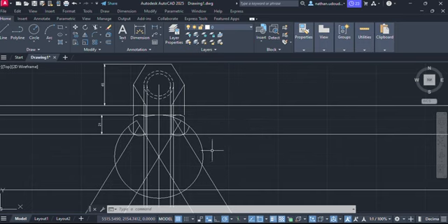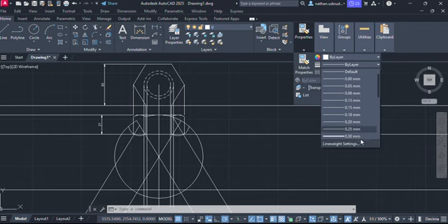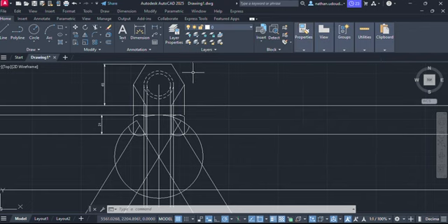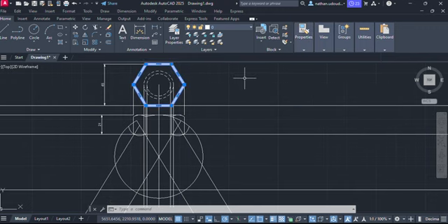to trim, because the work is looking a bit rough now. But before we trim, we can bold what we need. So let's come to properties, and let's take 0.7. So now let's highlight this, properties by layer, 0.7. Okay, so now